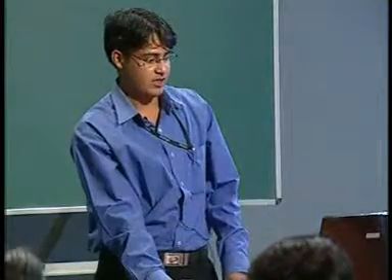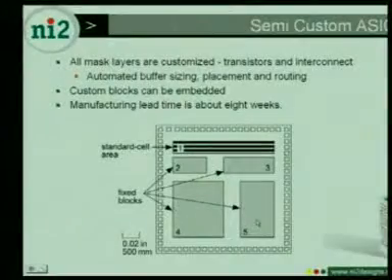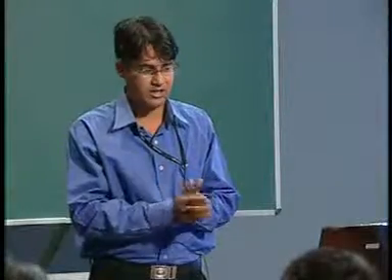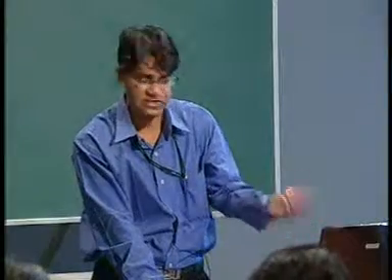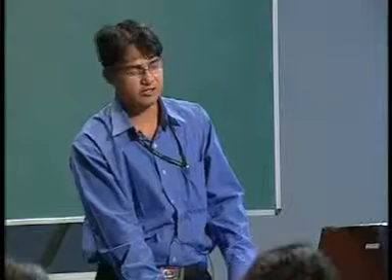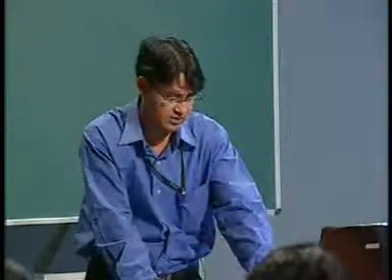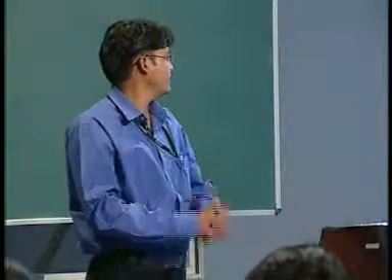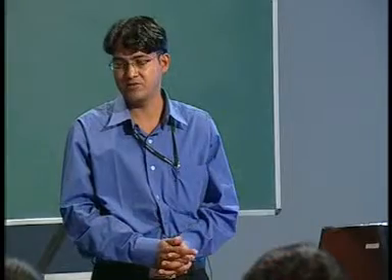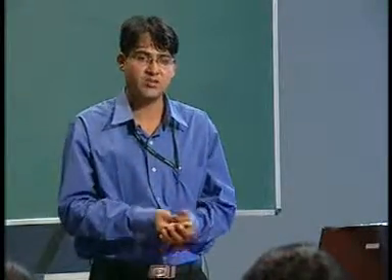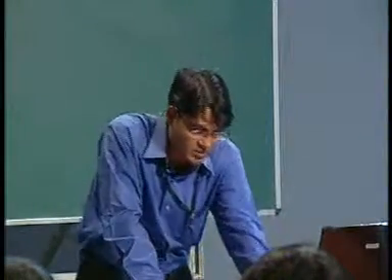In semi custom design, you already have some ready made blocks that you take from the market, and you plan the proper management according to the area constraint. There may be a few blocks which need to be designed, but others are ready made. So, it will definitely take less time compared to full custom, because there you start from the beginning. But you can't exactly say that it will be as powerful as full custom or not. The good thing for companies is that TTM, time to market, is less. You can develop a chip in a few months, like 2 months, but for full custom design you need at least one year maybe, because complexity is too high nowadays.